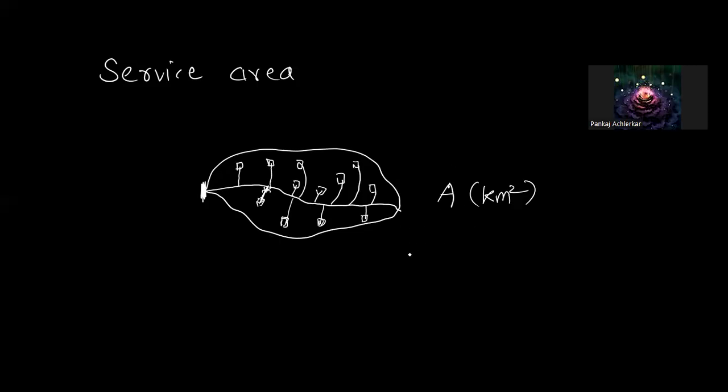And let us say we know how much total load is there in terms of kVA or MVA, basically the apparent power. So now, in order to do the approximate analysis, we need to take some assumptions. Since the load is located randomly at some locations, for detailed analysis we can take the exact location of loads. But for the approximate analysis, what we can assume is that the load is uniformly distributed throughout the area.